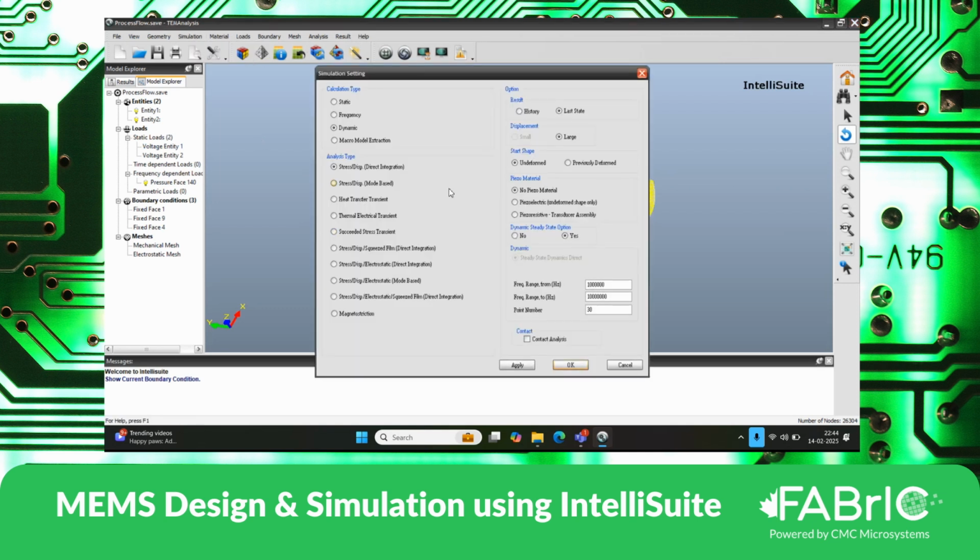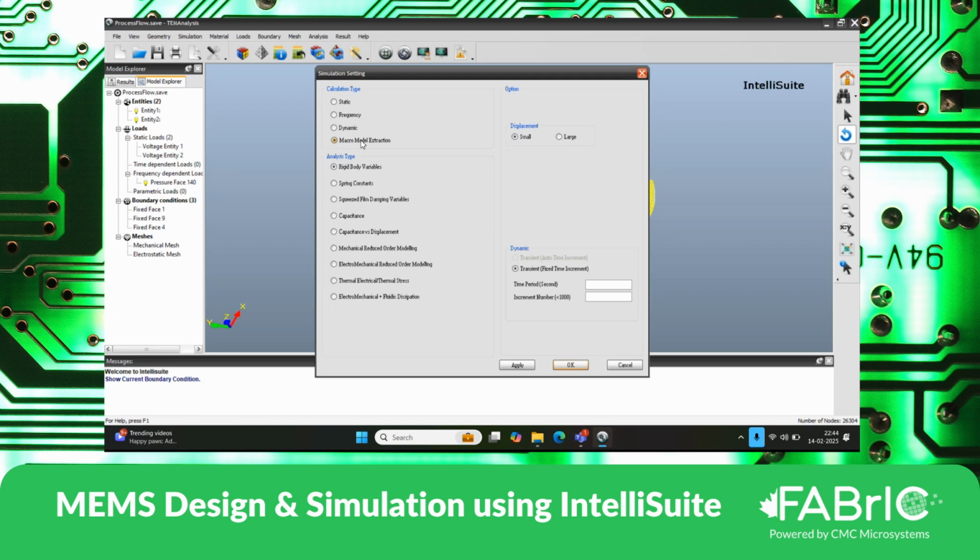Okay, to perform a system level simulation, what we do is we do a macro model extraction. In the case of macro model extraction, we have many other macro model extraction based simulation where it is spring constant, rigid body variables, squeezed film damping variables, capacitance.